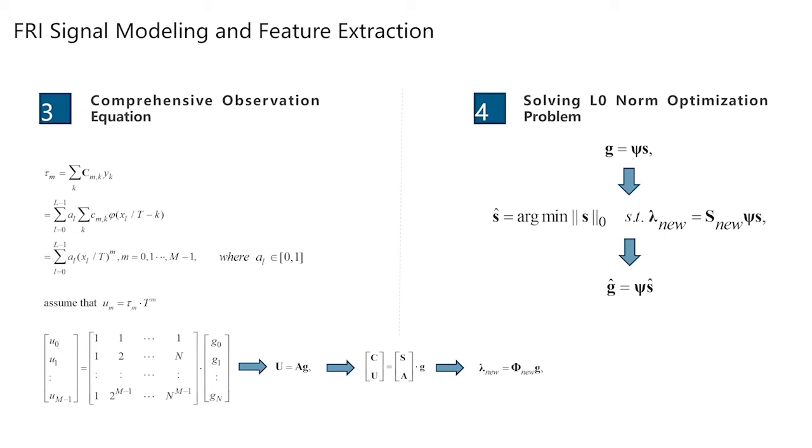Finally, signal sparsity can meet the reconstruction requirement, but the signal is not sparse enough in the ECT system. Therefore, the input signal needs to be converted into a sparse signal. The original signal can be transformed as follows. After orthogonal transformation, the signal becomes sparse. The sparse solution is usually obtained by solving the L1 norm optimization problem. In this paper, we use the orthogonal matching pursuit algorithm to solve this problem. So the estimation of the original image signal can be obtained.